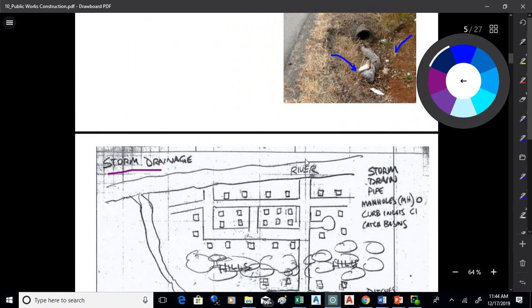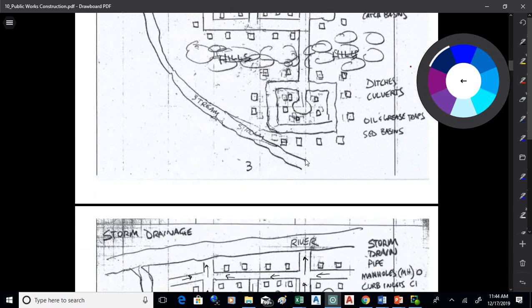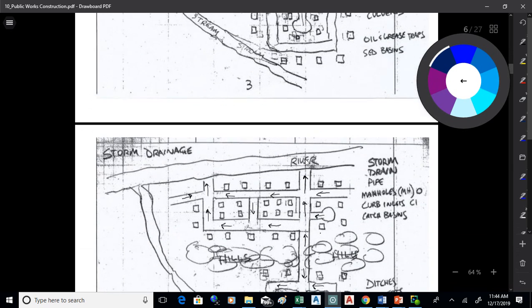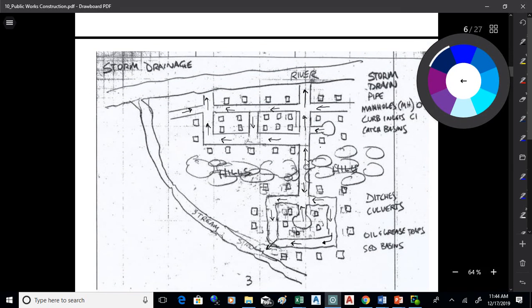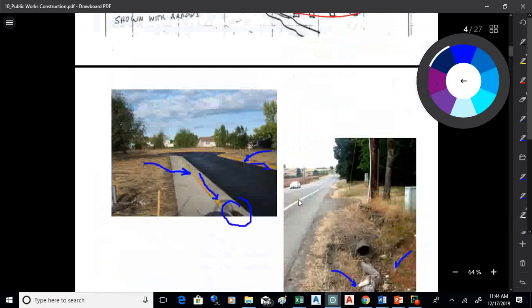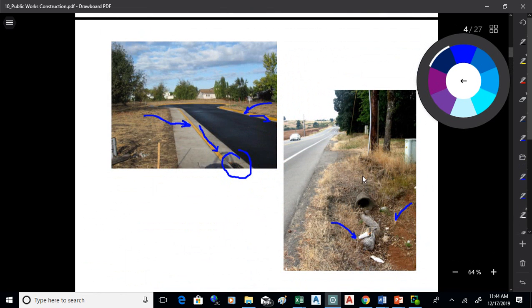All right, so the storm drainage and the road, those two systems are linked together. So you do have to consider how the water will flow across the road and then design a drainage system to accommodate that. You've got to have some system to get the water off of the road. That's the idea. Also, when you start building these roads without curb and gutter, they typically serve as dams and kind of run across the ground and can back water up behind them.